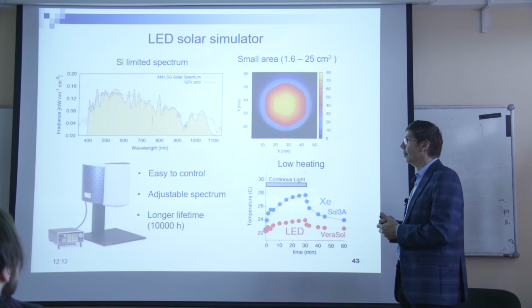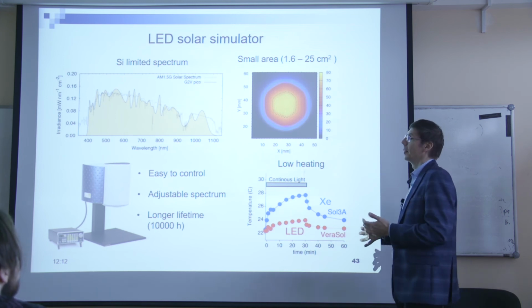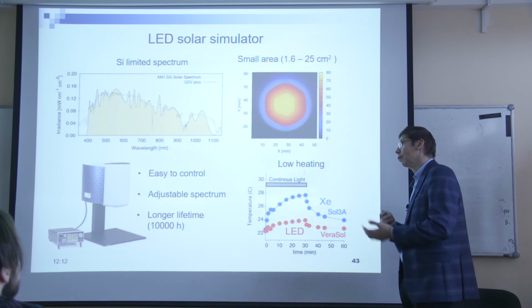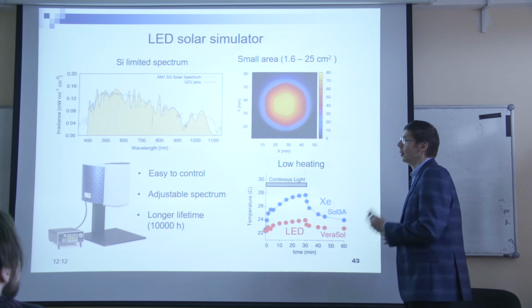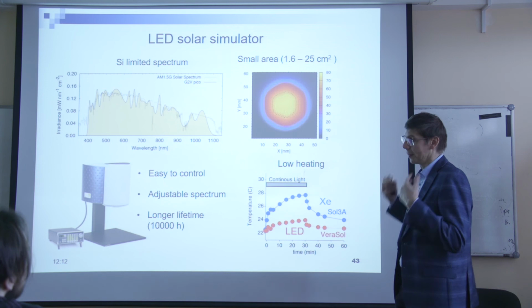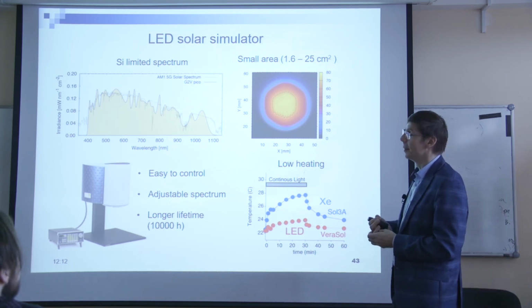is more or less achievable. Using a spectrometer based on silicon CCD, it's not so expensive, not so sophisticated. But for a wider range, it's a question, because you need an indium gallium arsenide CCD.